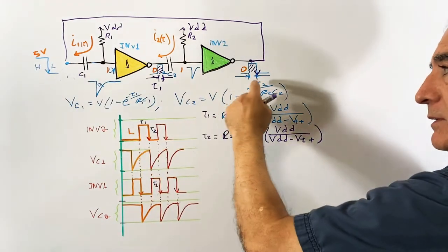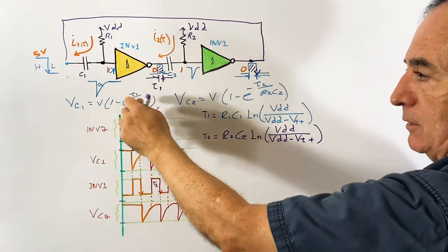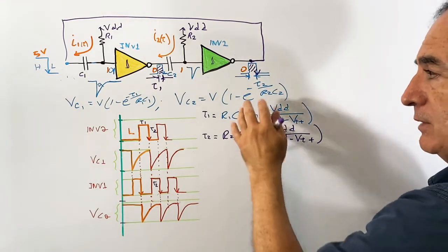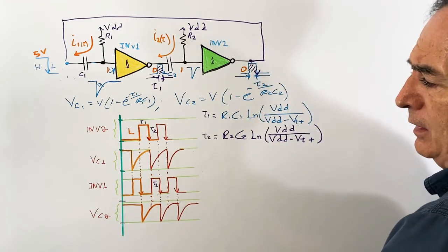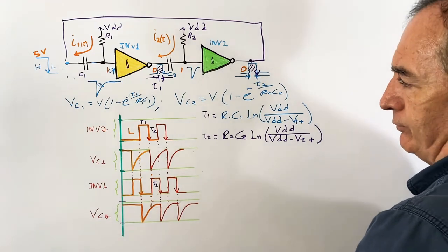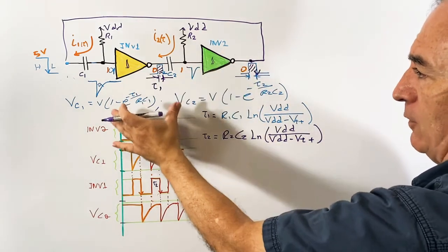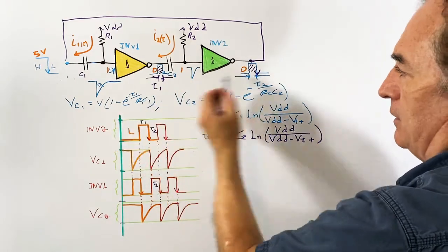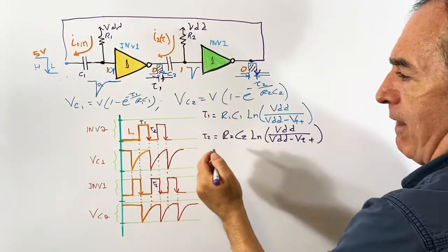So two edge detectors with a feedback loop can make an astable multivibrator, an oscillator we can call it. And so it works the same way. It triggers in sequence, and the feedback triggers again the circuit.